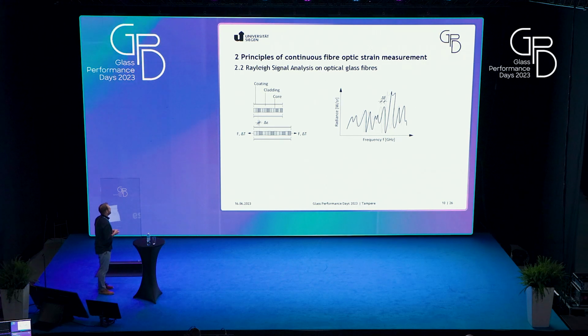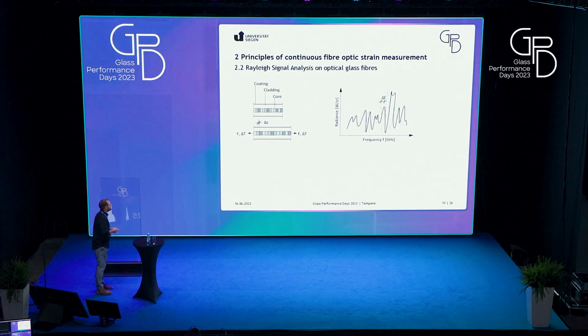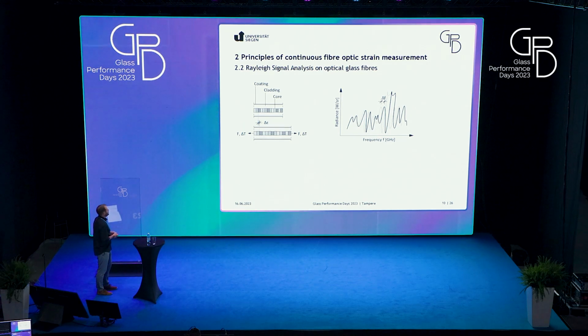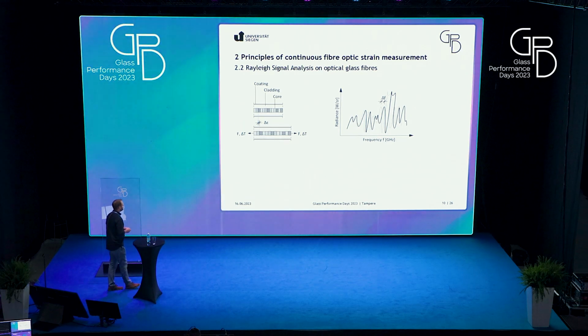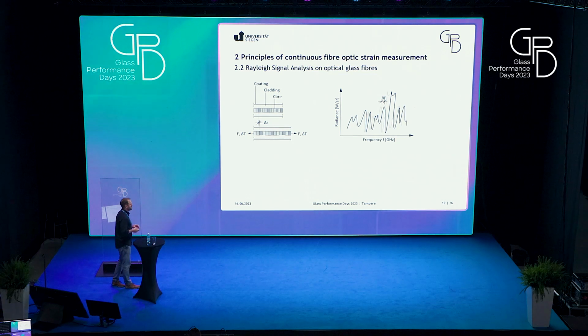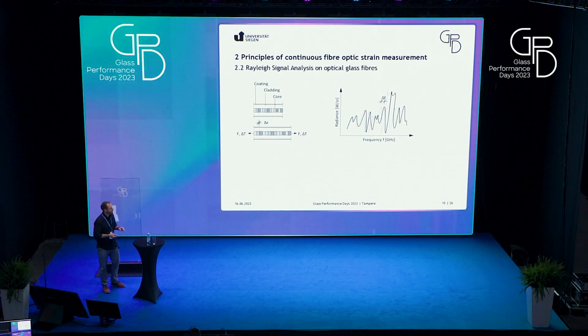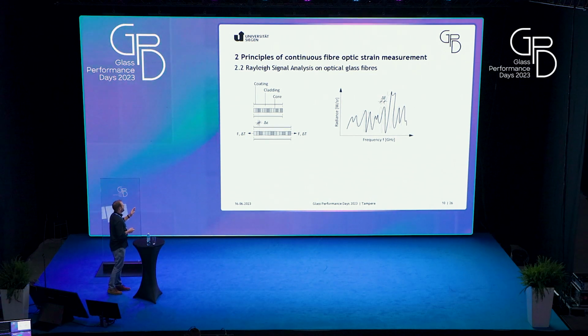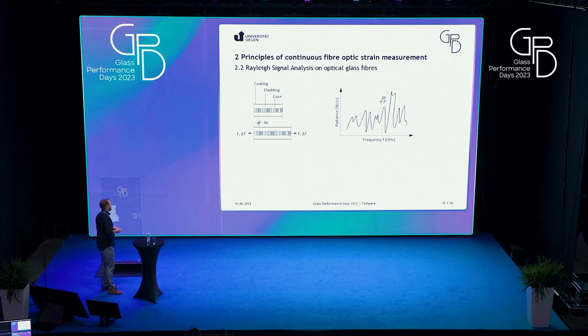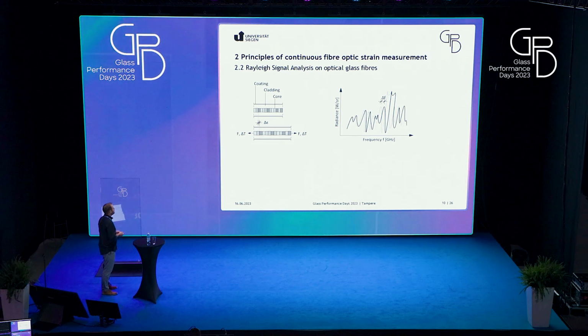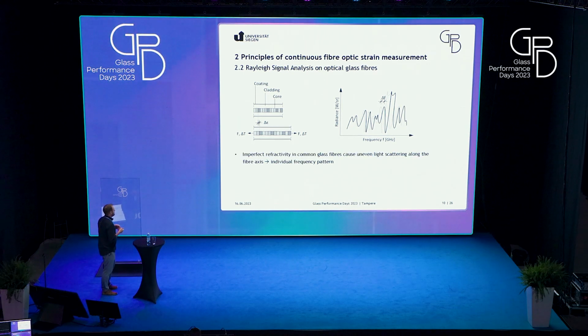And then we have to switch over to the principles of continuous fiber optic strain measurement. The left picture shows a cross-section of a common fiber that is used in telecommunication. This is elongated, force-induced, or by temperature. And these common glass fibers that are used in telecommunication applications